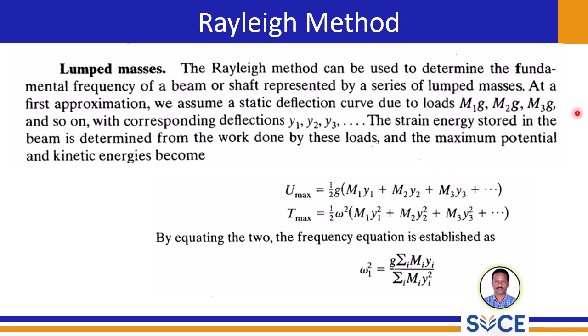So, it is very important that we are going to use lumped masses for efficient calculation purposes. We simplify the system by assuming the mass is concentrated at specific nodes, as per the lumped mass system. This is a common and often effective approach for analyzing systems with discrete masses, or as an approximation for continuous systems.